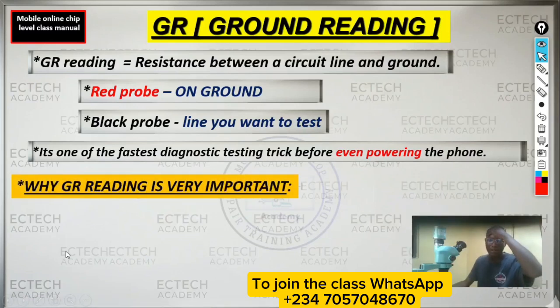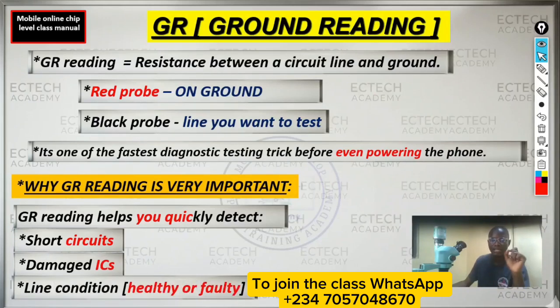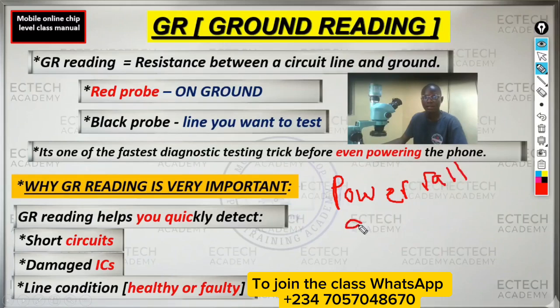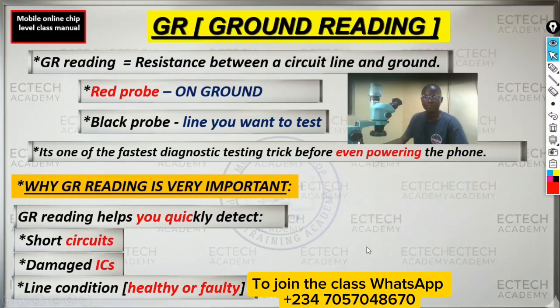Now, why is GR reading very important? GR reading helps you to quickly detect short circuits, damaged ICs, and line condition, whether it's okay or faulty. We have two lines we are measuring on the mobile PCB: the power line and the signal line. Also, we have the third one, which is just the general GND line. In order to know whether the line is okay or faulty, that's what we use GR reading to test.